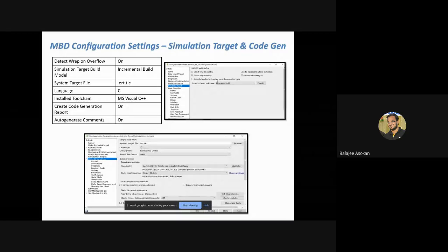It's not like if I miss something, because there are like 200 configuration parameters for a Matlab model, 250 at least, I believe. So it's difficult or impossible for someone to remember all of these parameters. But if this person is missing out on anything, whatever he remembers, he can make those corrections appropriately. Even in case he misses out something, he can run the model advisor report and from the model advisor report, he can fix it.